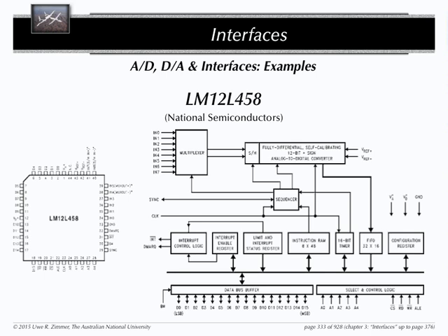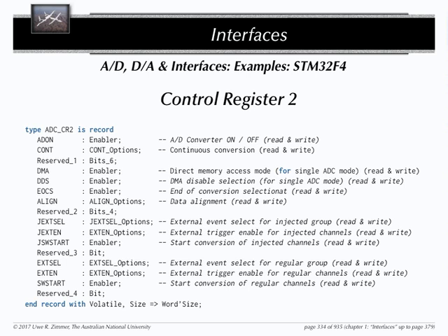You want to see some more real-world controllers? Okay. I just bluntly copied, randomly, one of the control registers which you have on your actual device on the screen here. This is control register 2 of one of your AD converters which you have in your actual machine. And this is the breakdown you have here: enable DMA, enable the actual controller, continuous conversion. It also comments which of them are read-write. In this case, it's a configuration register where everything is actually read-write.